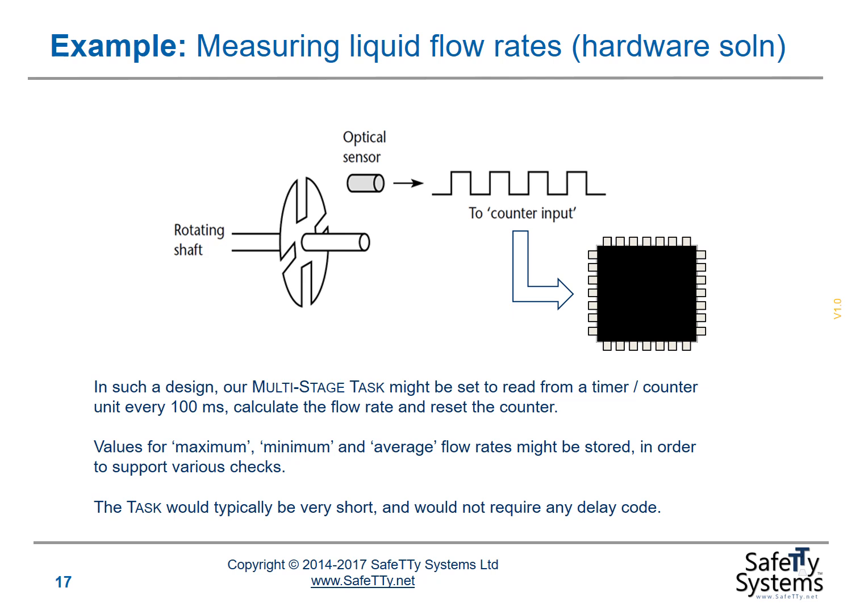So the timer counter input would carry on operating, counting the pulses that it receives without any intervention from the CPU. And we can typically do this up to very high frequencies. And the frequencies will depend on the particular hardware platform that you're using. But the frequencies you can support will be much higher than we can support using software polling.